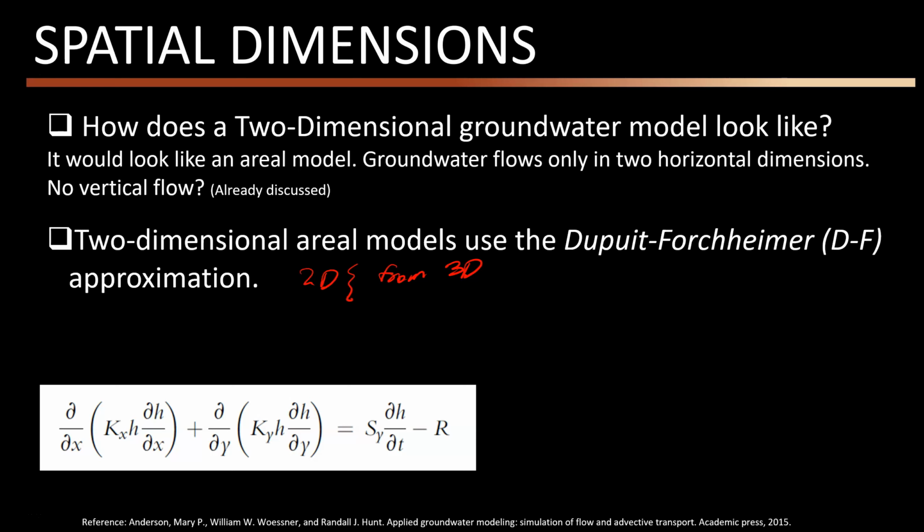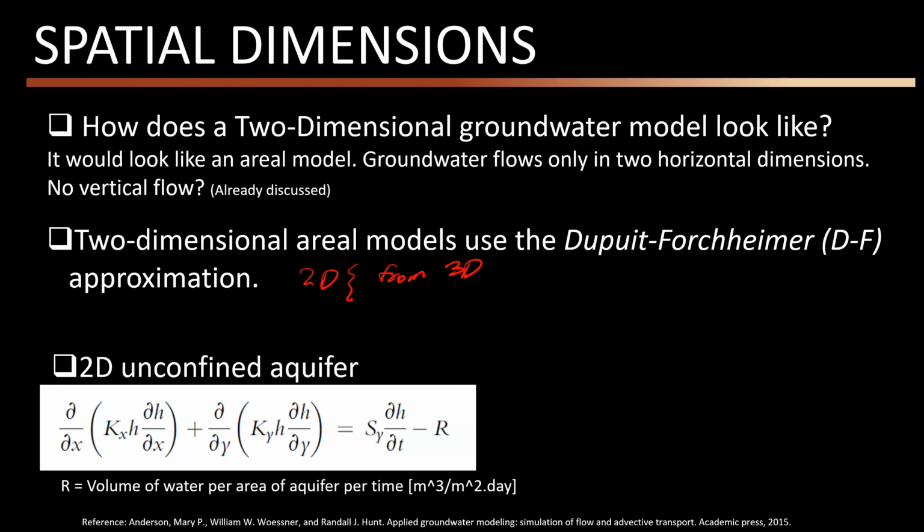But as you see, for example, here, this equation represents the head changes in x, y, and t in an unconfined aquifer. As you see, here I use the SY concept. But the thing that I would like to talk a little more about is the sign of this R. This is the sink and source term. If you remember, we call this a sink and source term. Actually, this is an external recharge or discharge term. And if you look at your notes, we had this R at the left hand side.